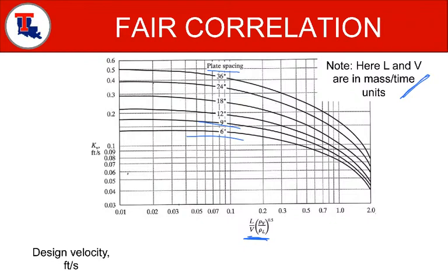Okay. So, what you would do is you would figure out what tray you're going to use. You will be specified a spacing. So you have to first calculate this L by V ratio or flow parameter. How do you figure out flow parameter? Well, this L by V ratio, GL by GG, you'll have to figure this out. Okay, we'll see how to figure that out in a minute. Because in absorption and stripping it was easy, but in distillation, how are you going to figure out the flow rates of L and V? Right? That's a tricky one.